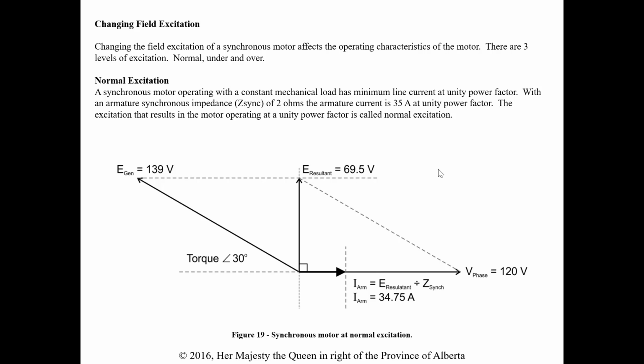So it's definitely going to have an effect on this torque angle here, by changing our field intensity, which will definitely change this E-gen. But they're saying the effect is going to be smaller, and that changing the mechanical load is still going to have the greatest effect on torque angle. So it will have an effect, but again, not as much.